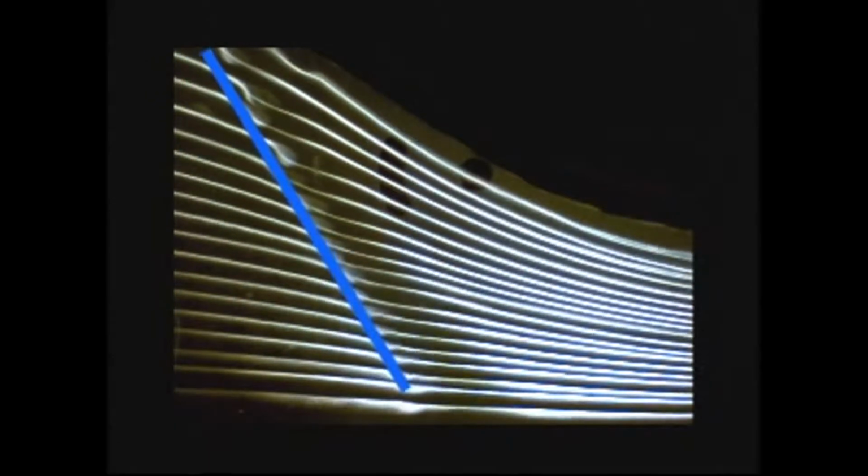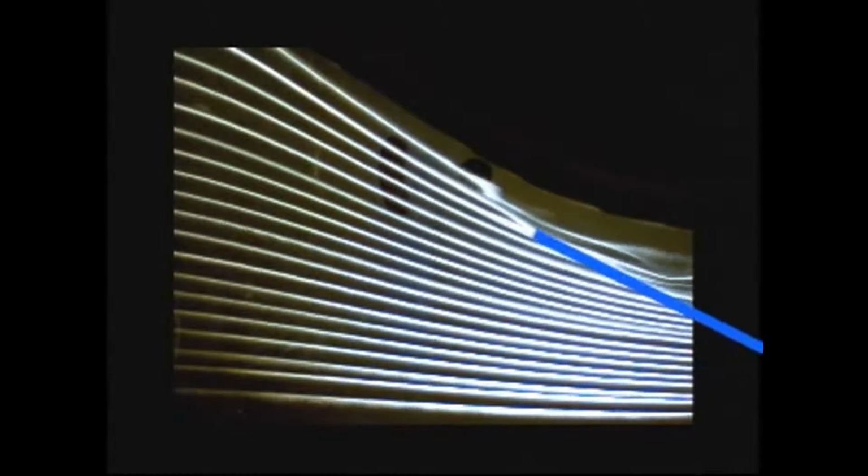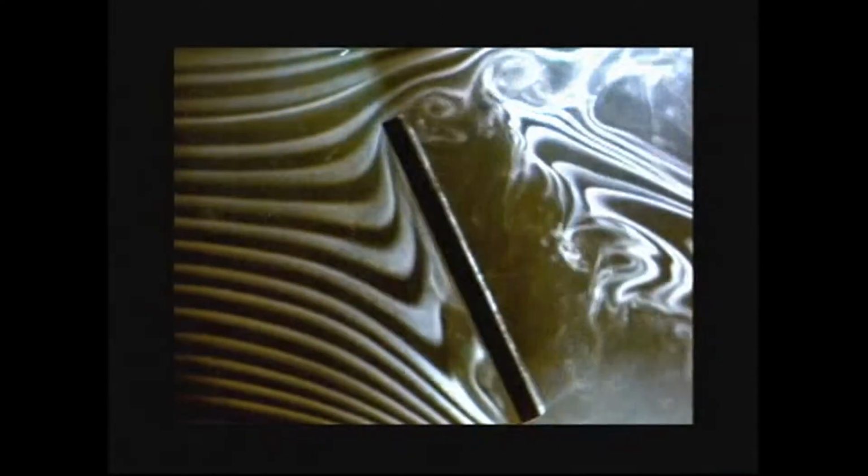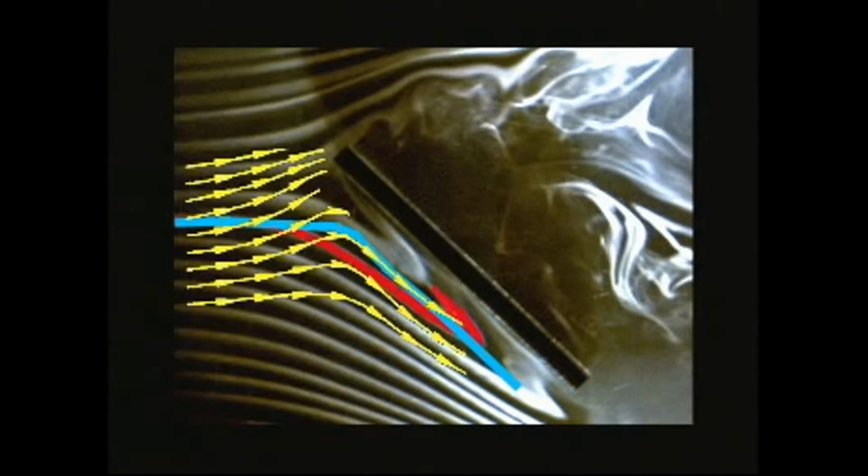A timeline is rather different. It is a line of fluid particles across the flow at a given instant, and it reveals the velocity profile. In unsteady flows, streamlines, streak lines, and path lines can be quite different. Here, the unsteady flow over a rotating plate is shown. When the flow is observed at an instant when the plate angle is the same as in the previous steady flow, we can see that all three lines differ. The streak lines and path lines, which developed over a time history while the plate was rotating, differ from the instantaneous streamlines.